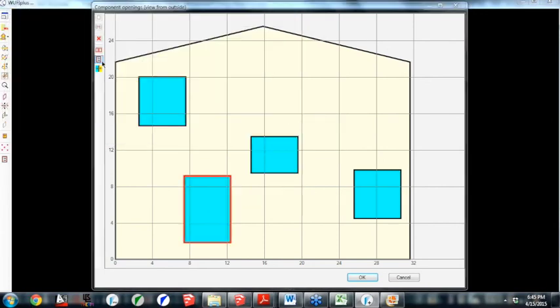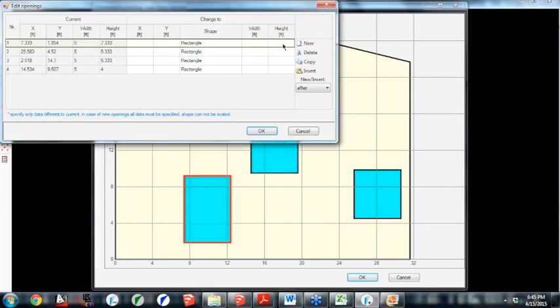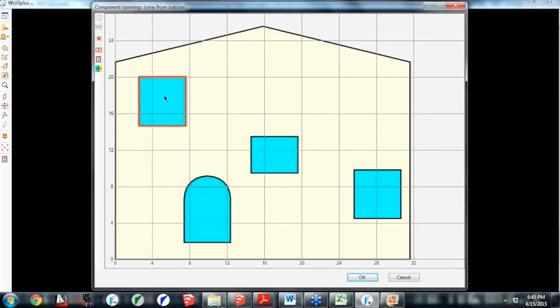You can also change the shape if you want something like that. So there's options to edit the geometry within WUFI Passive. The other thing is you can re-import the geometry and it doesn't mess up most of the stuff in your model. So if you're going to make a lot of changes, it might be easiest in SketchUp. It's up to you, but it's pretty easy to use this list feature.